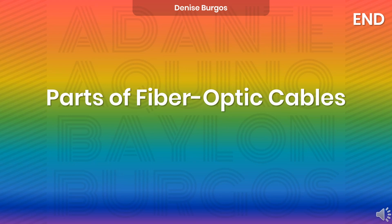Core, cladding, and jacket are the most basic elements in the construction of fiber optic cables. The jacket is for protection. The cladding is for the total internal reflection to occur since it has a different index of refraction from the core. The core is where the light propagates.